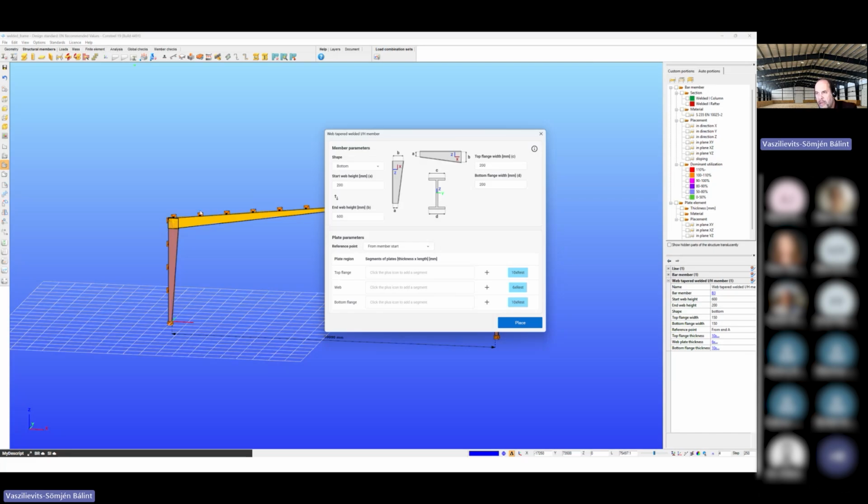That's part of Consteel. In order to define a member, I need to have first a profile. That profile is basically just an internal fallback profile. It's not necessarily the profile of the final product, because I can change everything by myself. So for example, I can change the width of the flanges freely. It doesn't necessarily need to keep the one which was used for the creation of my starting beam. I can override that flange width the way I want.